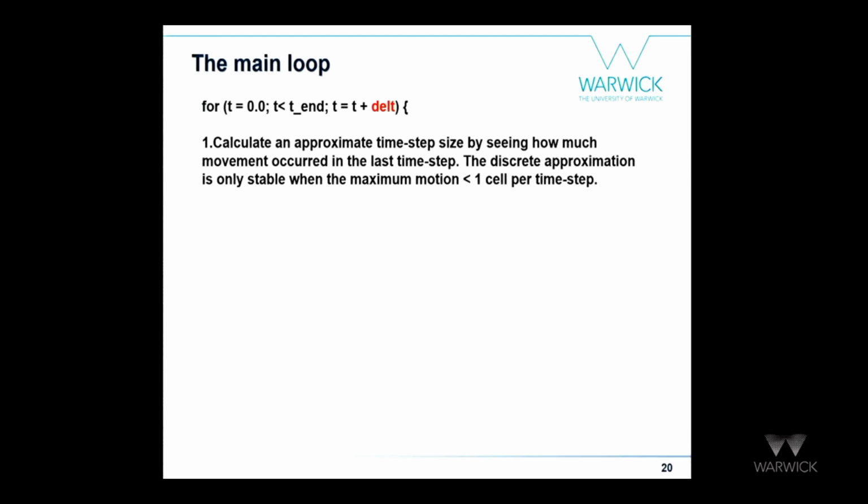And according to mass conservation, the amount of fluid flowing into the area should equal the amount of fluid flowing out of the area. Right? So that's why we need to first calculate the time step. In the code, we look at the current velocity of the fluid, and then adjust the time step so that it will not flow more than one cell in one time step.